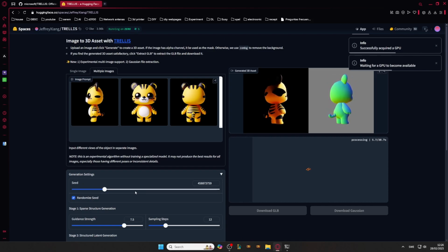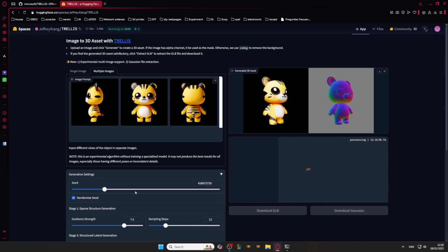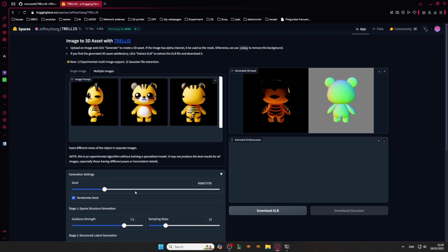And when you're extracting the GLB, how long it takes depends on the simplification steps. So the less simplification, the longer it takes. If you go to 0.5, let's say, it will take twice or 3 times as long. But considering you don't need to model this by hand, it's pretty good. It saves a lot of time if you're going to do something from scratch.